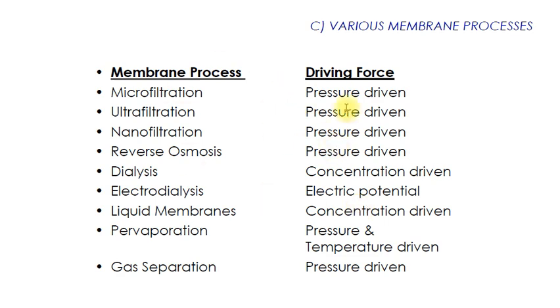There are four different membrane-based processes especially used for water purification: microfiltration, ultrafiltration, nanofiltration, and reverse osmosis. In all four of these processes, the driving force is pressure.